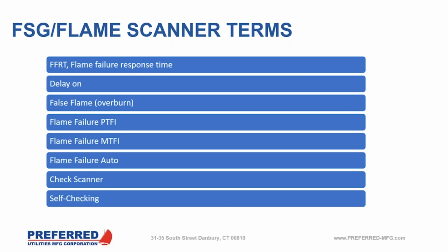Before we actually get into the flame scanner technology itself and the different types, it's very valuable to understand the different terms that are used when you're talking about the flame safeguard product and how it responds or how it's used when combined with a flame scanner. One of the first terms is the flame failure response time, or FFRT. You'll hear this quite often.